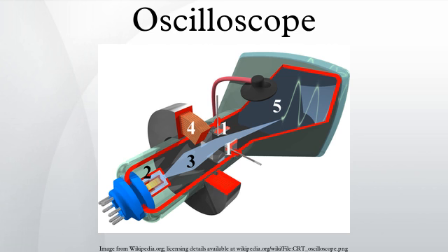The green line is the waveform, the red vertical partial line represents the location of the trigger, and the yellow line represents the trigger level. If the scope was simply set to trigger on every rising edge, this waveform would cause 3 triggers for each cycle. Assuming the signal is fairly high frequency, the scope would probably look something like this, except that on the scope, each trigger would be the same channel, and so would be the same color.